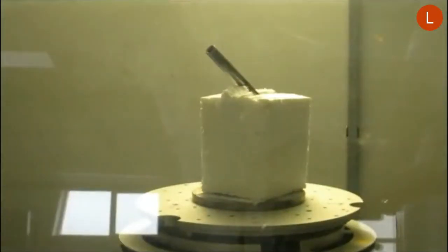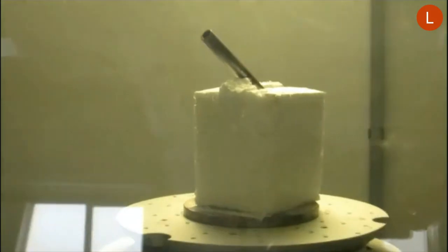The scanned part must be fully visible in the scan window, and then the process of scanning can be started, in which it is necessary to set the number of projections and the filter used. In this case, a 3 mm thick copper filter was used, and activate the correction of the acquired images, which will form the 3D model.